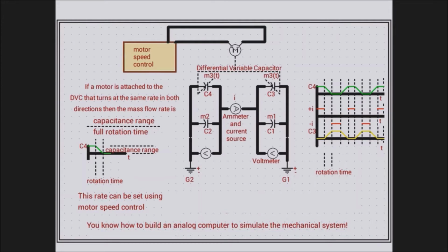we now reverse the polarity of the current source, and this is the equivalent to a force trying to pull the two masses together. We let that go on for our desired amount of time, and the voltmeter measures the voltage waveforms that result. The ammeter measures the current waveforms, and from these waveforms we equivalently divine our voltage and velocity events in the mechanical circuit.